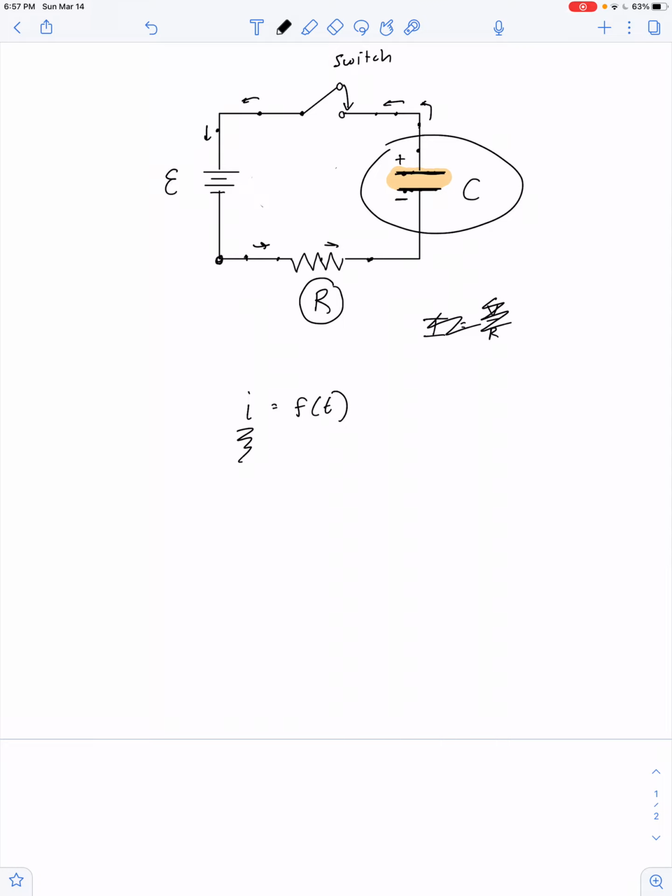I want to start here at point P, and then I'm not saying necessarily that current is flowing this direction. I just say I'm going to trace my way around the circuit like this. Actually, I'm pretty convinced that the current is going to go in a clockwise direction. Now, that current doesn't go through the capacitor, but that clockwise symbol right here for current lets me know that current flows to the left through this resistor, and I need to know that in order to determine the polarity of that resistor, right?